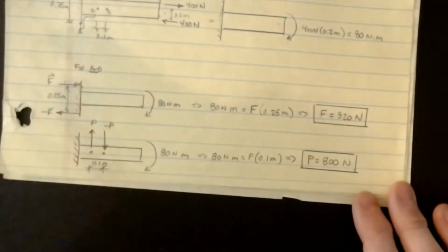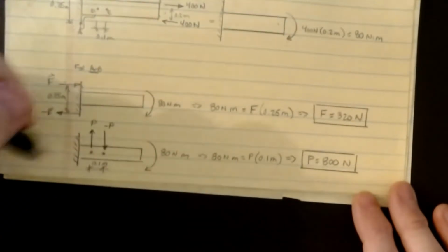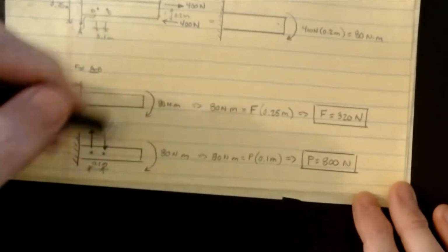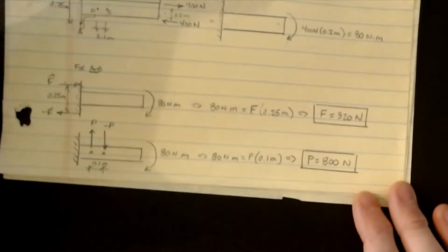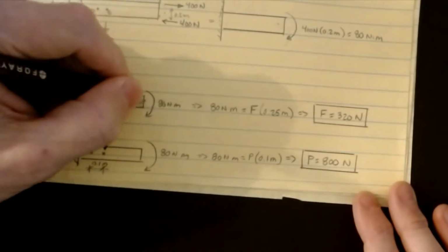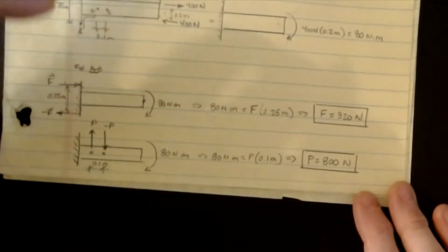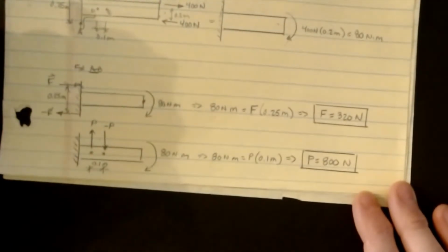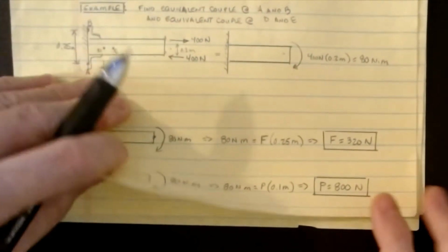And I can put these couples anywhere that I want, and I can move the moment around, because the moment is a free vector. And that's the definition of a free vector. It can be applied anywhere. Even though I started out saying we're going to apply it here, it can actually be pushed anywhere, and I can find out the equivalent effect at any other location, kind of doing some games like that. And we'll do a lot more with this. This is kind of an equivalence problem as we start to look there. All right. Okay, so I think that's all we have.